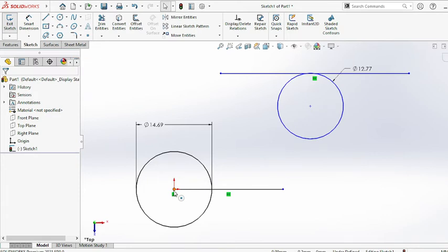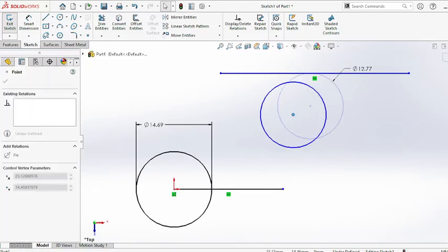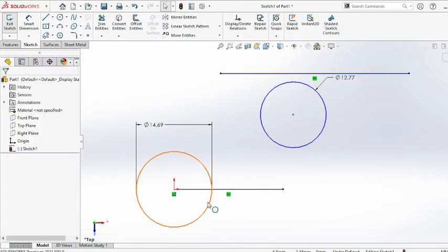See, you can observe this one will be in blue color, and this one will be in black color. Why? This figure will be in black color, that figure will be fixed. Fixed means I am specifying the position of that. I have specified its position and given it the required dimensions. I will apply all the dimensions and specify the position of that also, and that time it will be in black color, meaning it will be fixed. Fixed means it is not moving, but this one is moving now.